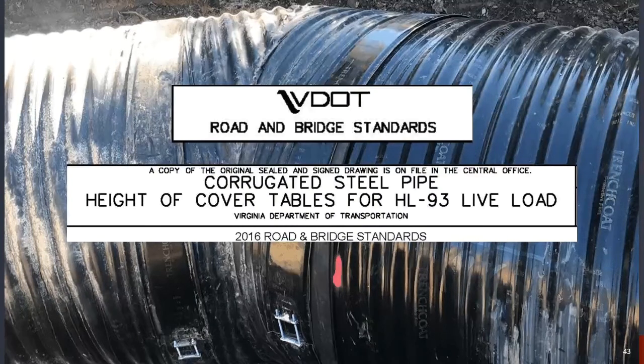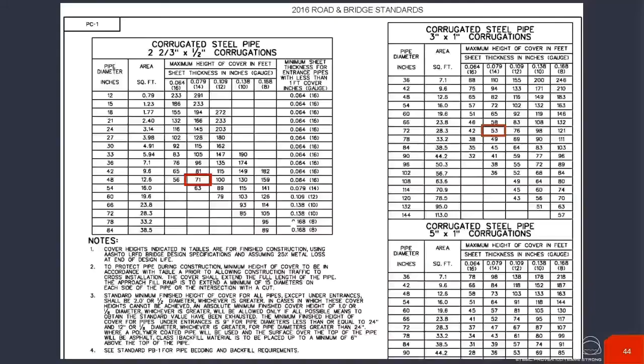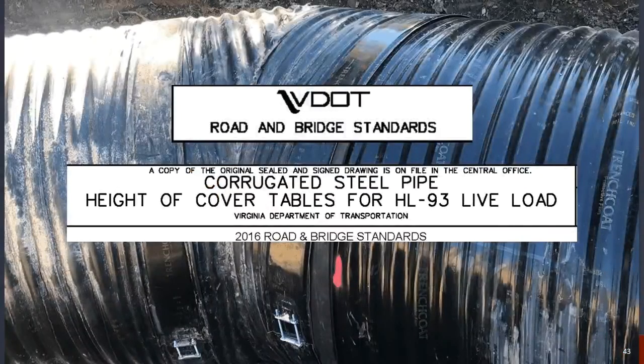So, gang, just to wrap things up, how are all of these applied in state form? Daryl shared the tables that we had developed, the AISI tables, and all of those are available in Chapter 7 of the Corrugated Steel Pipe Design Manual. I'm going to look at a couple of state examples just to highlight how they've implemented this. So this is from VDOT. VDOT has developed tables just like we did, implementing LRFD HL93 loading.